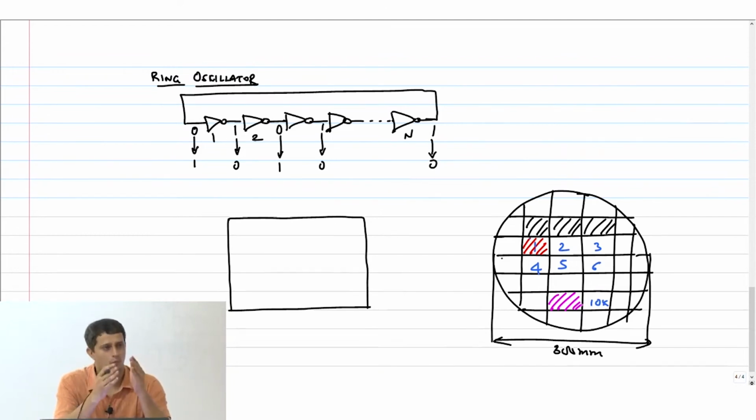Your level 1 model, like we spoke about, has parameters VTH naught, gamma, and so on. That VTH naught can shift slightly, right? Instead of 300 millivolt, it can become 350 millivolt. All the transistors in that chip, by the way, that's what I mean here. Every transistor in this chip 1 can have a VTH naught of VTH plus delta. This magenta one, every transistor in this can have a VTH of VTH minus delta.